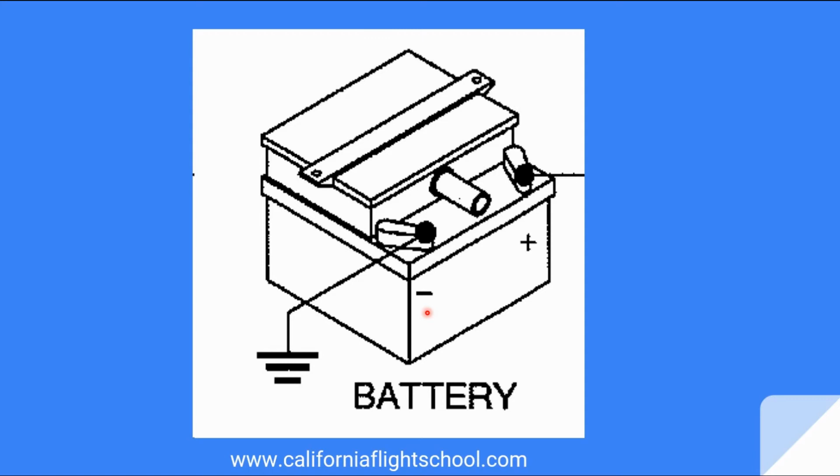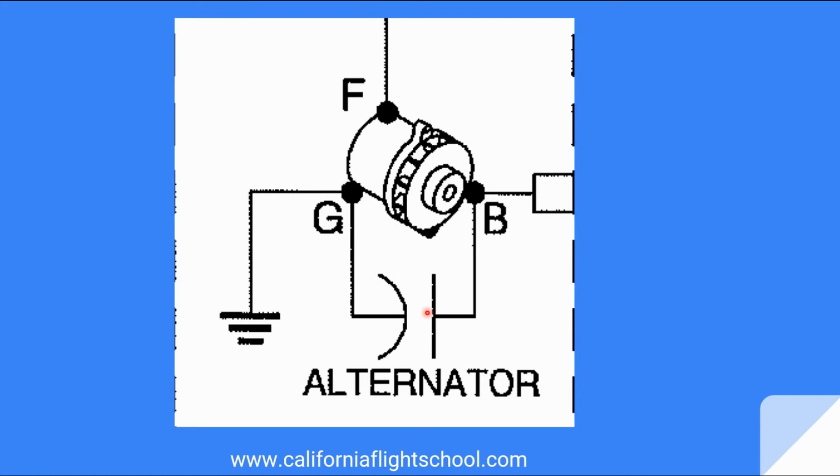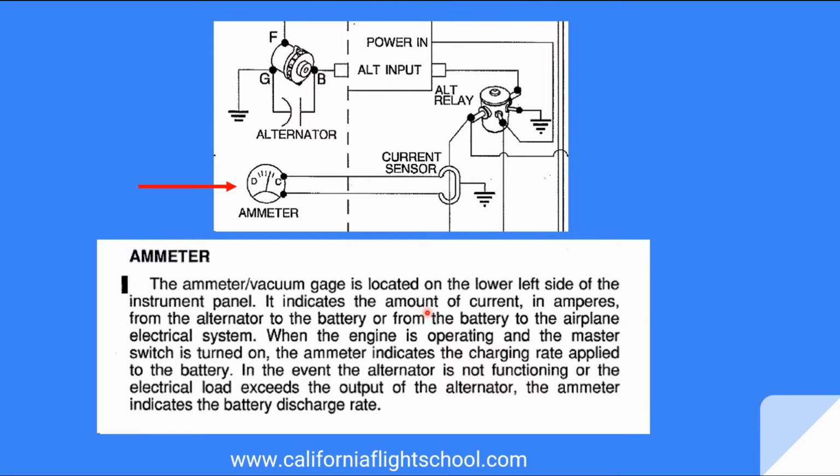So we'll talk a little bit about battery, how can it be charged, can it be removed from the aircraft, is there an auxiliary or a ground power plug in the aircraft. Talking a little bit more about alternators, what makes them work. They're belt driven, and once that belt goes, well, so goes the alternator. It's not going to be producing any output anymore.